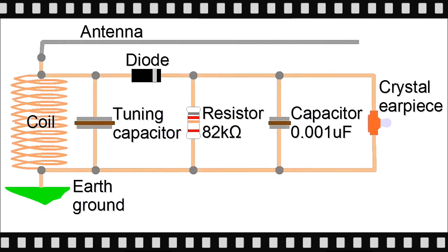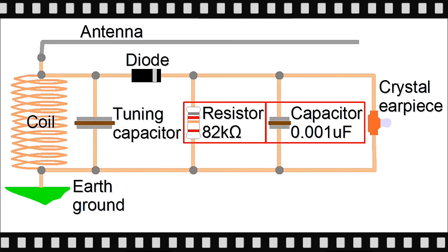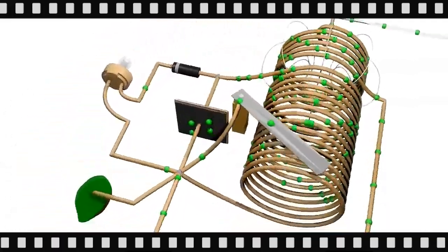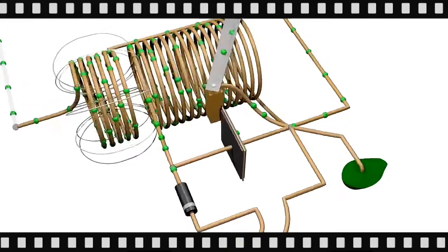This one's almost identical to the one I've been describing, except that there's only one coil. That means it has poor selectivity, meaning it's harder to tune into just one radio station at a time. But it has higher sensitivity, meaning more volume. Notice that it also has the resistor and capacitor that I mentioned as good additions. And then there are a large number of other possibilities to play with, and things to learn about. So if you haven't already, make one and go from there.